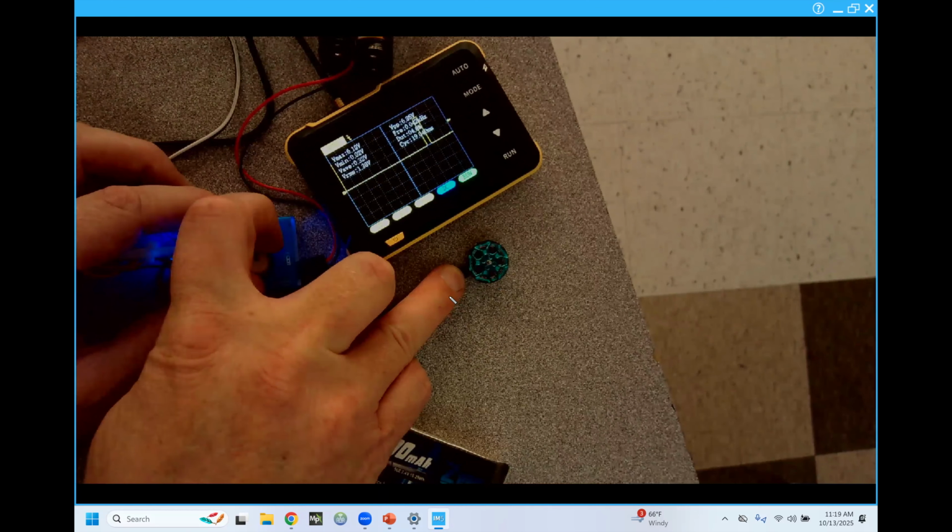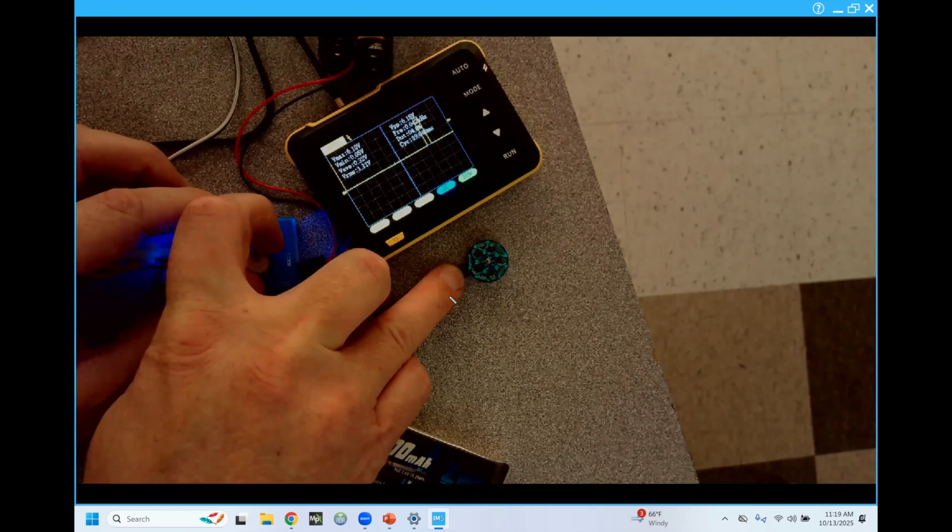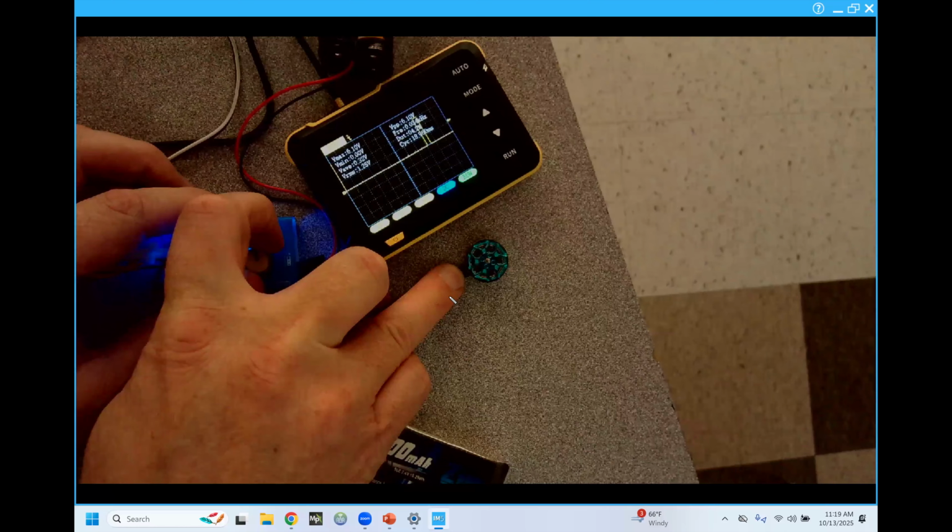The flight controller will send a PWM output to all 4 speed controllers, and then it will determine how much thrust each motor should provide in order to fly the drone.